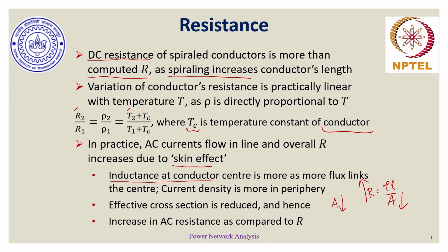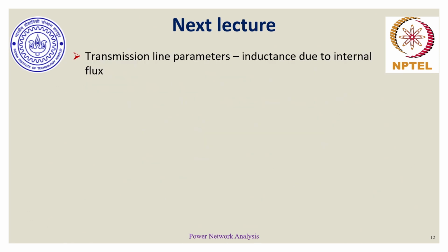So AC resistance is always more than the DC resistance, and calculating the overall actual AC resistance is not an easy job, because again, modeling or countering the skin effect requires a lot of detailed analysis.